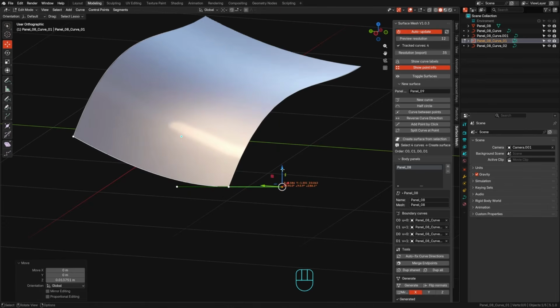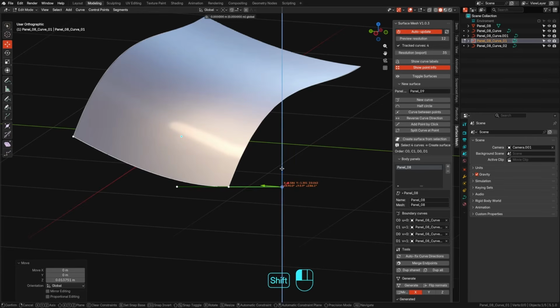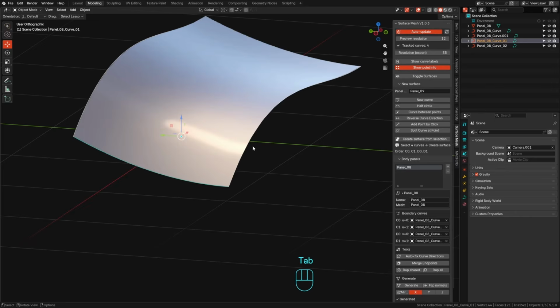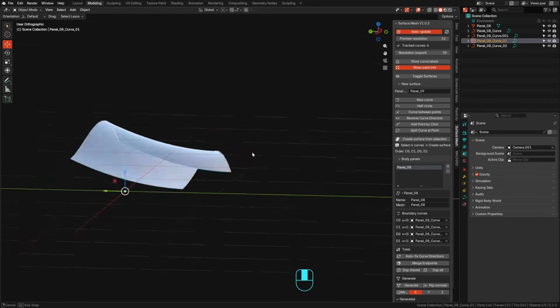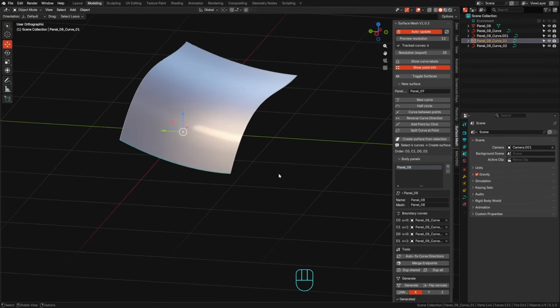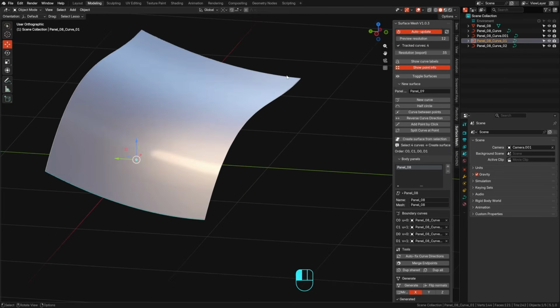This means I can set this value from 86 degrees to 90 degrees here. Using Shift allows for fine-tuning, bringing it exactly to 90 degrees. If the connecting surface is flat, I know it will connect smoothly. I know it connects continuously. I will do the same with the second curve to ensure seamless continuity.